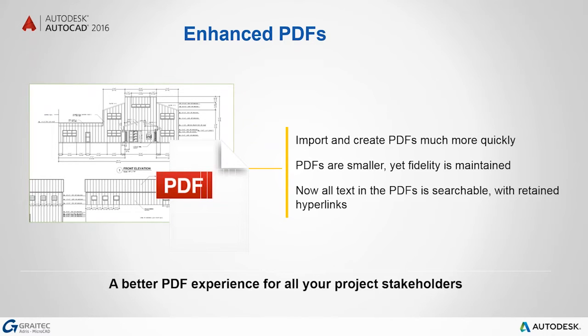Regarding the comment about the increased fidelity and the resolution of the PDFs, these days, whether you're exporting to PDF or printing to PDF, you will find in the print dialog box we have got a new PDF options button, and in there it gives you access to change the DPI of your PDF. So if you are finding particular drawings are looking a little bit grainy or a bit bitty when you produce a PDF, then these options should allow you to increase the DPI of your output.